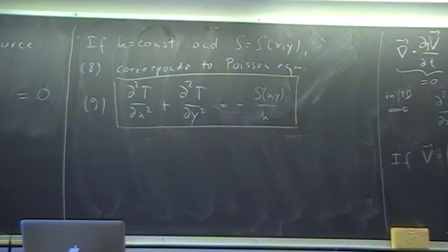And when we discuss temperature, we can, in the same sense, also treat concentrations. So then we would not have the steady heat equation with heat source, but the steady diffusion equation with a source. We would not have T, but C, a concentration. We would not have k, but D, the diffusivity. But otherwise, we would get the exact same reasoning.